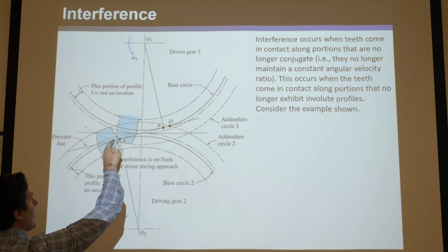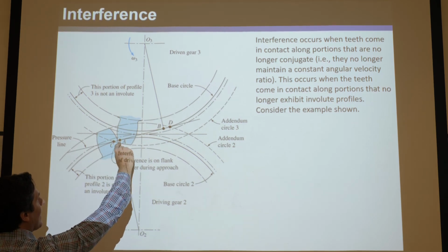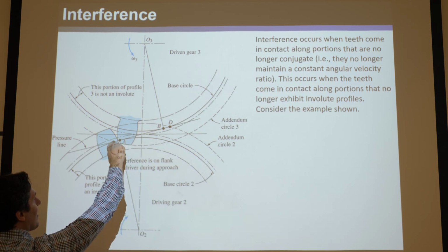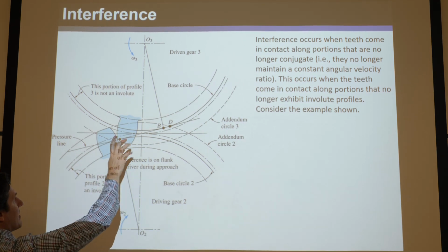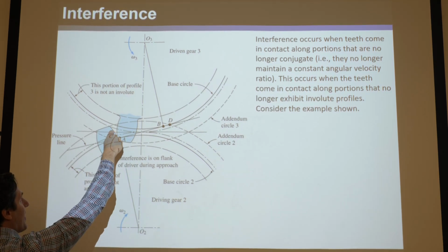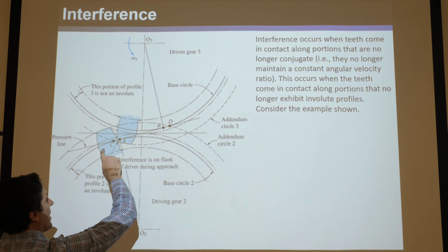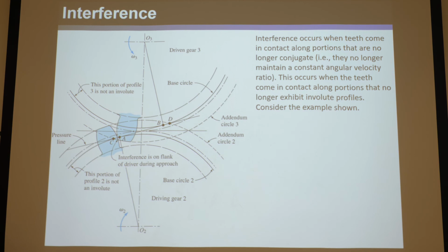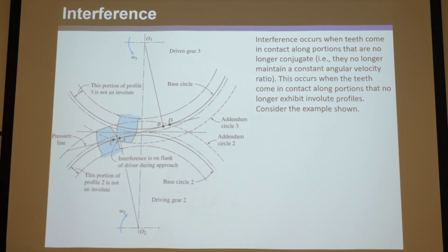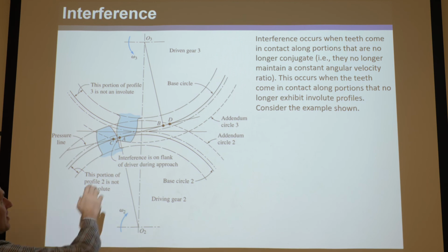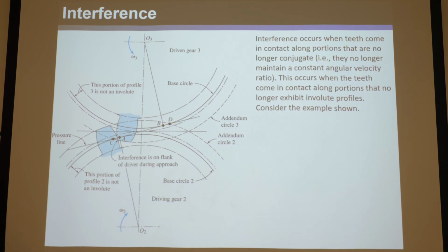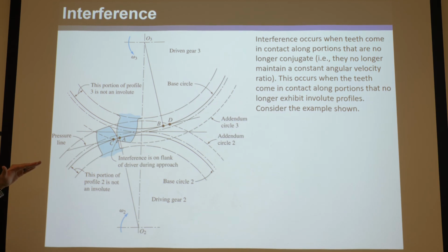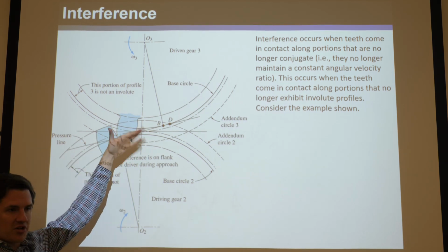But if A and B are between C and D, then when this gear first touches at C, moving from C to A, this edge right there where it first touched at C on the addendum will scrape down below the base circle of this tooth as the whole gear mesh moves from C to A. And below the base circle of the tooth cannot be involute. So for the entire time of contact from this tooth to that tooth between C and A, they're touching along non-involute profiles.